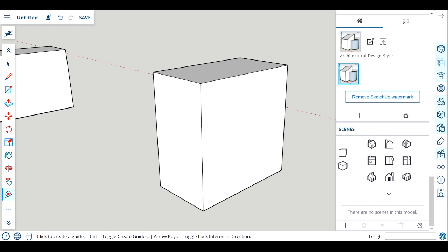So starting with that guideline, I'm going to go ahead to the bottom and give the bottom of my file cabinet to the beginning of my first drawer. I'm going to give myself a 4-inch space. So I'm going to select the end point and I can just type in 4. And now I have some type of guideline created. I can elect to just leave my point in here, or I can actually now draw in my line that gives me my 4 inches.